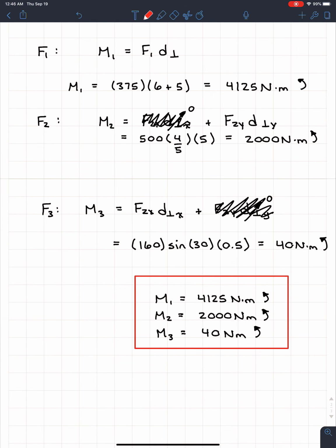And in structural engineering, it's one of the biggest things. One of the biggest challenges we have is increasing the span between columns. So the beam that runs between columns, making that span as far as possible. And it's not to do with strength, it's to do with moment. Because if we have people acting at that center of the beam and we expand further, it's going to create such a big moment because of the distance between the person on top of the beam and the column.